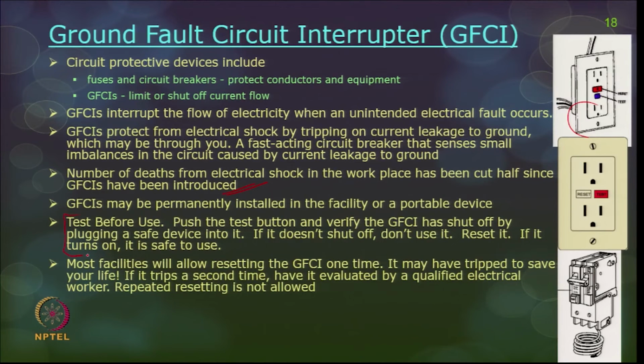But before you install or use the GFCI, test it before it is used. There are two buttons here. Push the test button and verify the GFCI has shut off by plugging a safe device into it. If it does not shut off, then it is not safe to use. If it is fine, then reset it, and if it turns on, then it is very safe to use.